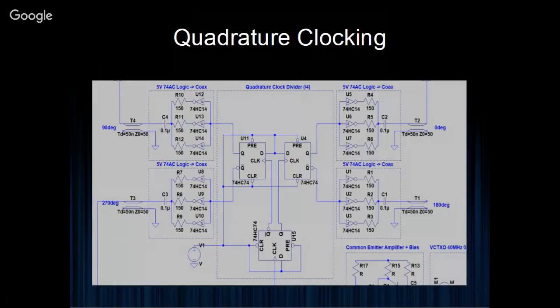When I design logic, it is best to go for a family that supports 3.3 volt and 5 volts, just to give you the flexibility to change the system depending on what accessories you might have connected, whether the clock gives a 3.3 volt CMOS output, or a 5 volt.